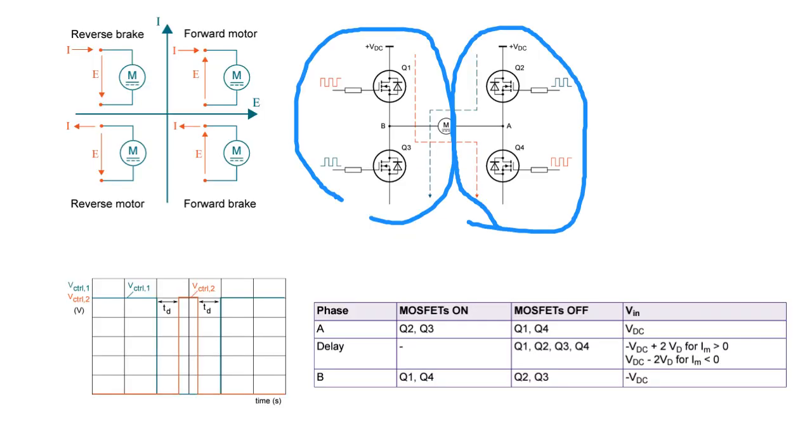Now, H-bridge theory. What is the H-bridge theory? Okay, we defined the DC motor parameters. We defined the effect of the DC motor parameters. Now we can start H-bridge theory. The H-bridge, also known as a full bridge actually, because it is a combination of two half bridges. It means that a full bridge is an electronic system consisting of four switches and capable of creating a bidirectional current and reversible voltage across its load.